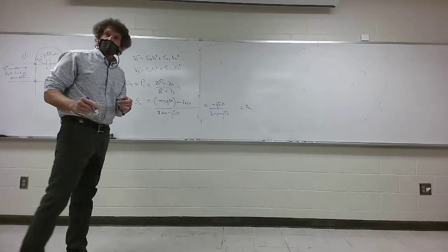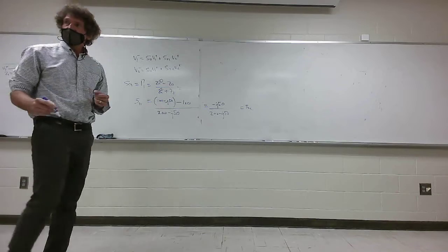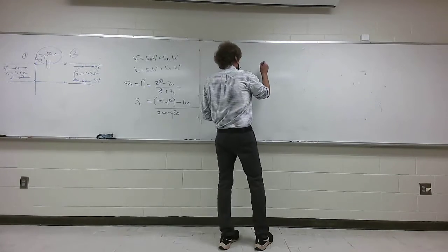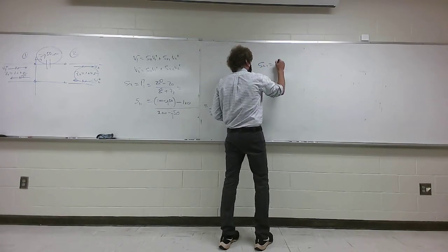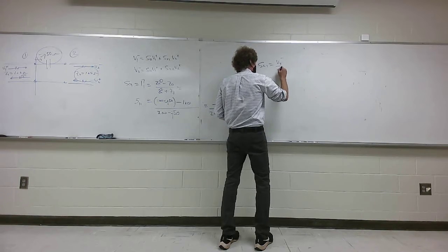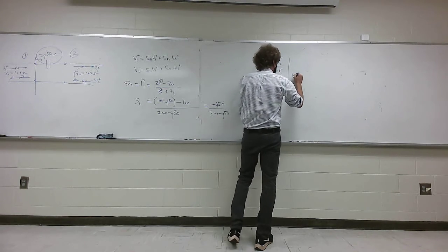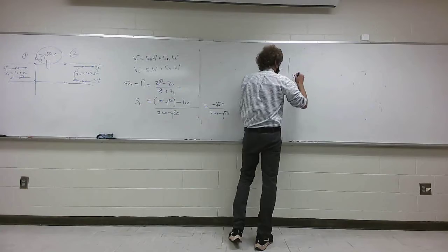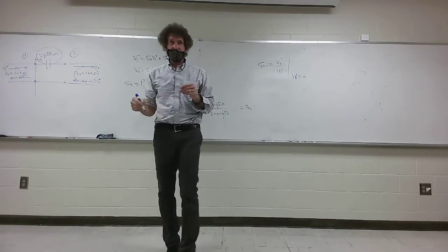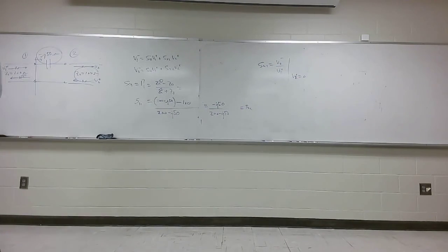Now, what is S21? S21 is equal to V2 minus over V1 plus, assuming V2 plus is 0. That's the forward voltage gain, isn't it? Guys? All right, so what is it? Well, here I'm going to have my V1 plus coming in, and what am I after?